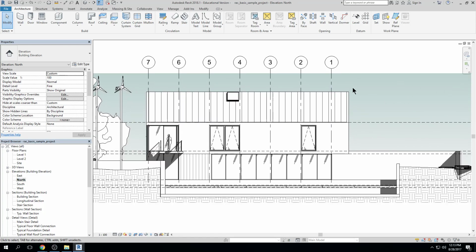We have some element terminology in here that we need to talk about. We have a host, we have components, we have views, datums, annotation, and levels. So a host is a built-in place element such as a roof, a wall, a floor, so construction elements that stand alone in a project. So I can come into Revit, open up a floor plan view, and create hosts by themselves.